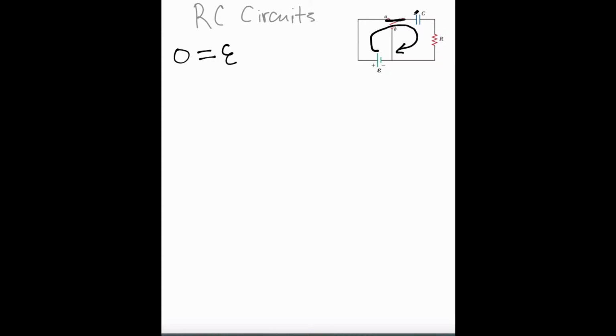The capacitor will end up with this being the positive side and this being the negative side. So once this does reach its full charge, meaning that it will reach the potential of our battery, then it's going to actually act against this loop. We describe that by saying q over C, where q over C is the voltage at some time t. That's, by the way, why I used a lowercase q here.